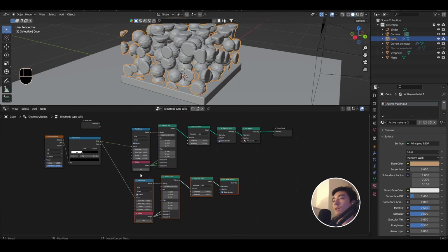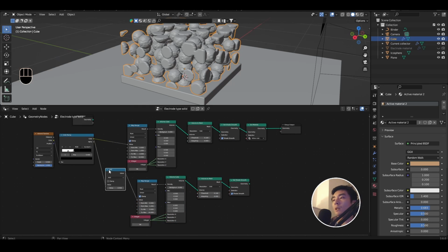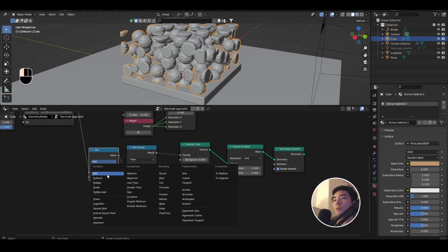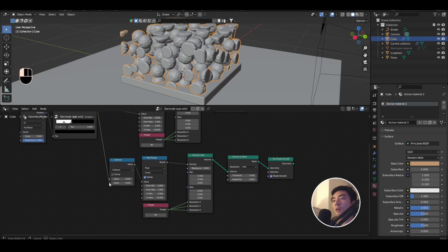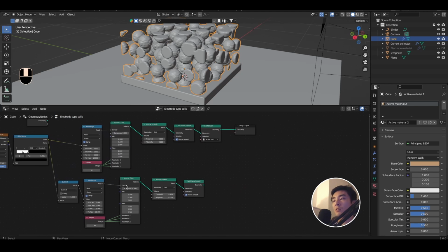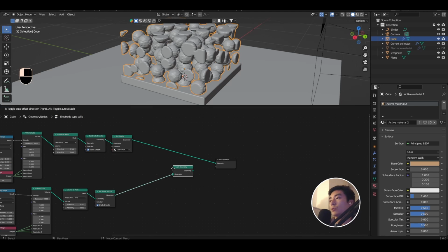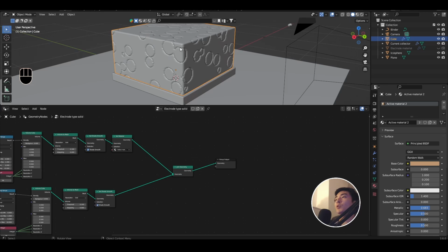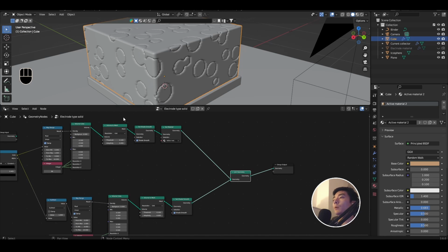Press Ctrl-Shift-D to keep the connections and duplicate. And then let's add a math node, plug that in between the color ramp and the second block of nodes we've just created. And we basically want to do a subtract operation and take 1 minus whatever density distribution we're driving with this texture. If we now take the output of that, join it with the output of just the active material part of the Voronoi texture, we should end up with a complete volume cube, though there are some pinching effects happening where we join them together.